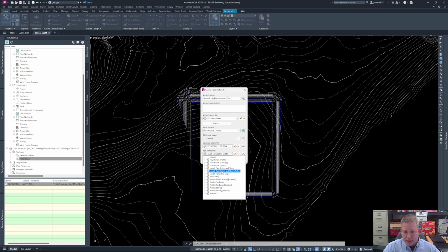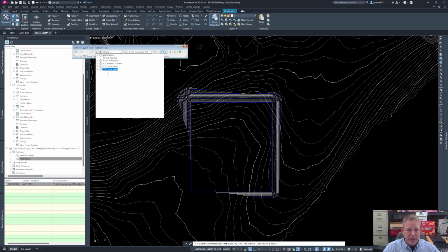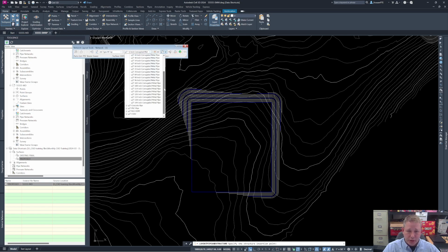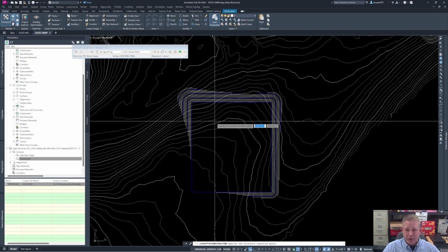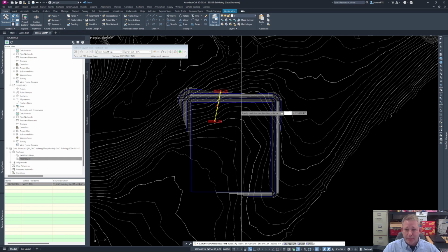So let's say I put a flow arrow for sanity or for storm. Get in here and I say, okay, I need my type M inlet, 2x4. Surface existing final, or existing file, yep. There we go, okay. Pick our pipe, let's do a 24. And we're going downstream. So we can click that there. And let's put that somewhere around in there.